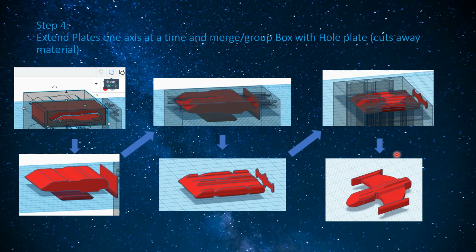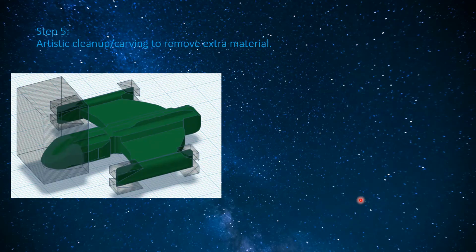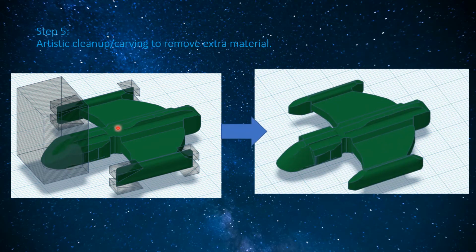One thing I will note here is these 3 views are not going to give you a perfect representation of the 3D model. I mean, you can kind of see here, this is supposed to be rounded, but it's not. So this will require some extra steps if you want to make it look cleaner and nicer. So here, for example, I'm showing doing these diagonal cuts with these objects. This is actually a semi circle cone there to basically round that off. So with that, you see it looks much closer and better.